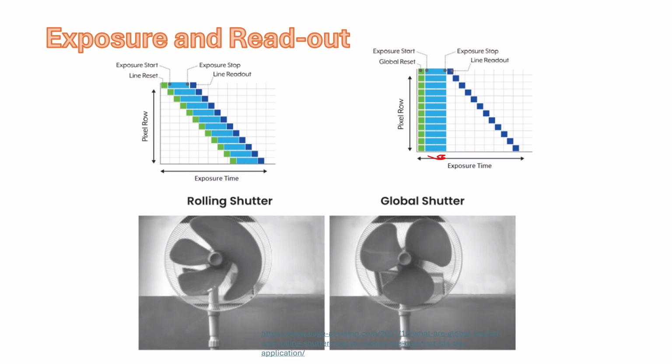And so once you've got to a range where you're not saturating, you're going to stop exposing for the rest of the frame time, and so most of the pixels are going to be lost. So the actual quantum efficiency of most sensors is poor, because the exposure time is typically much less than the frame time. This is a very unfortunate aspect of the current design of cameras. Event cameras are one solution to this, but they're maybe too focused on processing individual pixels. There are much more innovative ways to imagine exposure control, but they're not implemented in current sensors, so we need to deal with that as we think about how to manage images taken with real sensors.